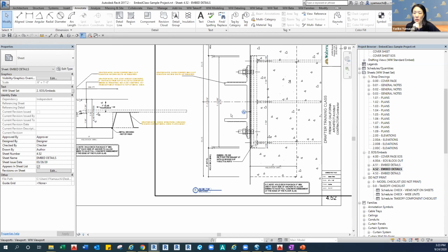Okay, I'm not sure if this is answering your question or not, but the name of the embed package, or the Edge of Slab embed package, sometimes makes people misunderstand. We only have to show Edge of Slab and also embed. But the Mac clip or any steel component, like sometimes we have a steel shelf that's also used by the field, and that information needs to be included within the embed package as well. So go ahead. Go ahead. Yeah, go ahead, Mike. On Santana West, yes.